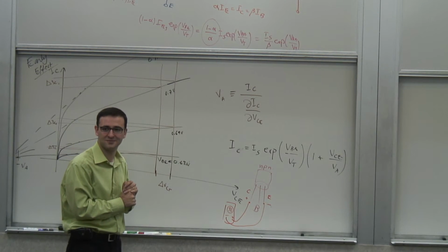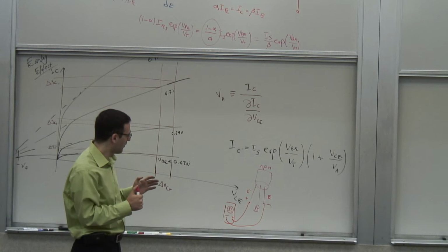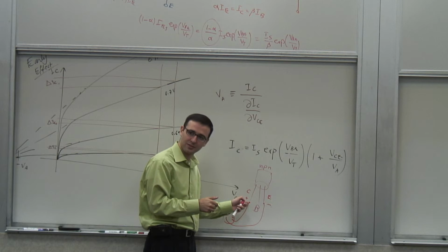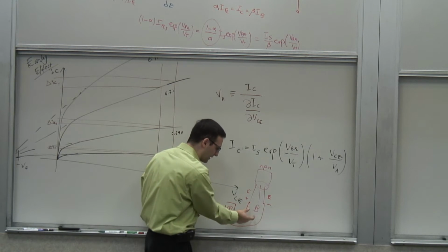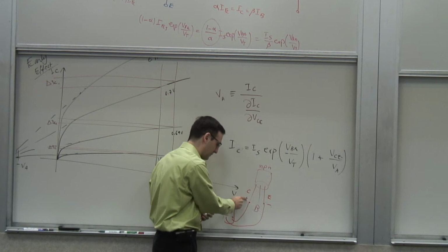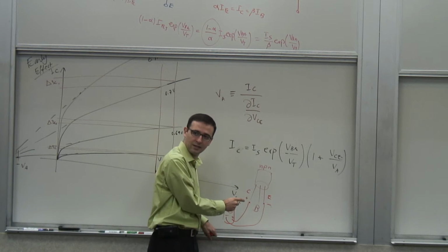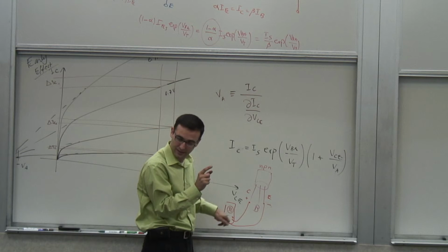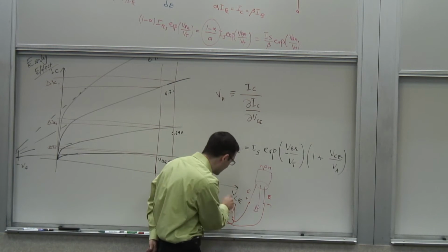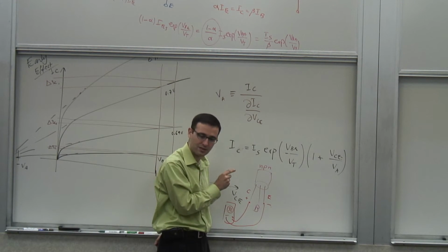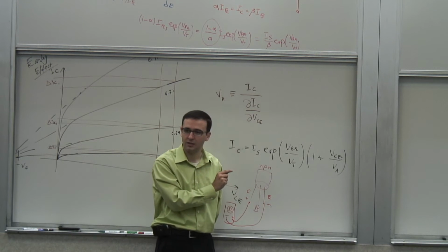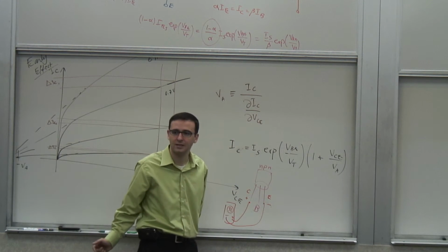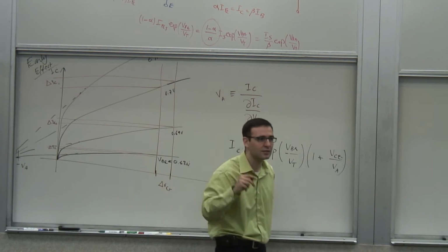Can you say the case one more time? Okay, so I'm connecting the positive terminal to this guy. Think about it as a battery. I'm applying a small battery between the collector and emitter, positive terminal to the collector, negative to the emitter. If I touch this and I see the resistance drop, then this is the collector, this is the emitter. If I don't see it change, it's the other way around. This is the emitter, that's the collector. And you can verify that by swapping and trying it again.